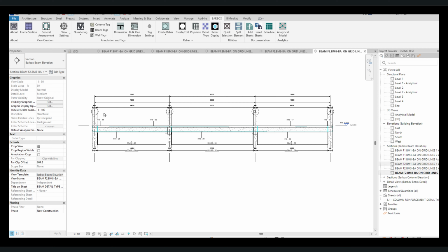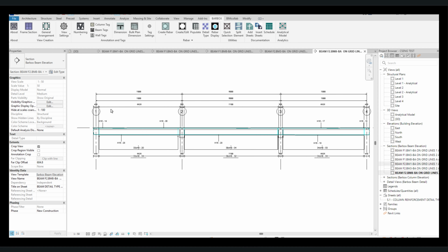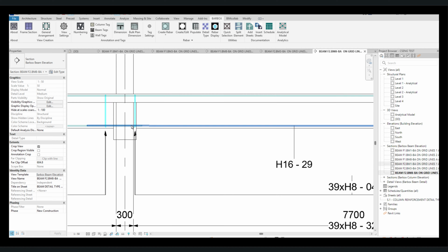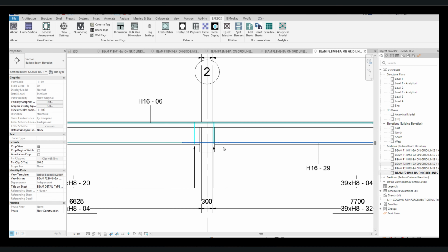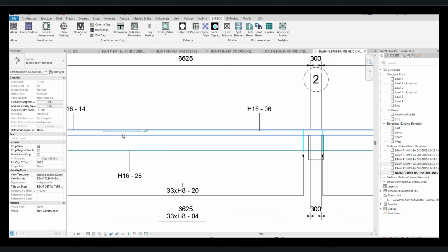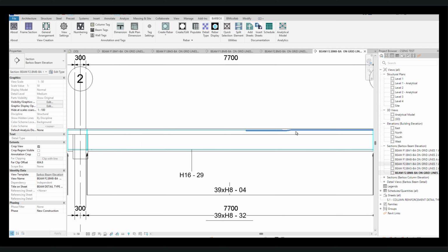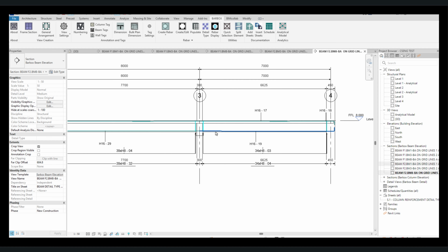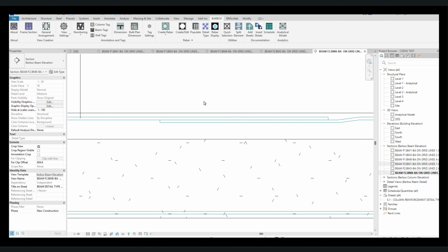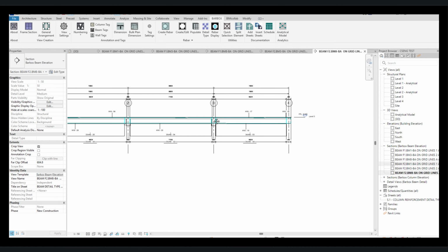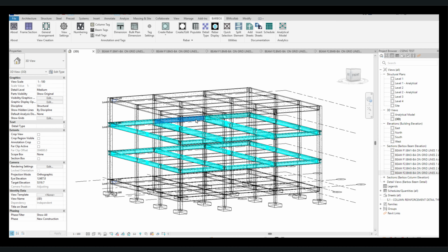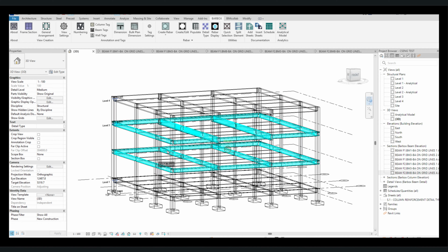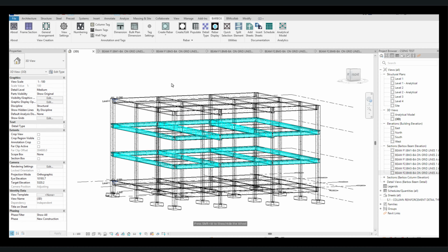Once you have a working template, you can assign those templates in the view settings, such that when you create a reinforcement detail type and check the detailing types and the crank options, all the labels are properly shown. Okay, so in brief, that is bar box. Thank you.